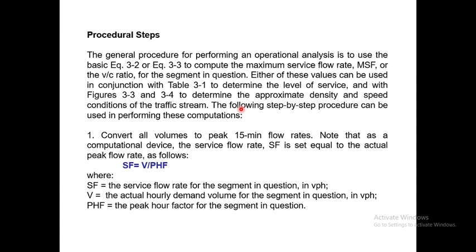The other equation which is very useful here, and in the first step very important: you have to convert all the volume to a peak 15-minute flow rate. So for converting, you have to use this equation. SF, or service flow, which is desirable for us, we always use SF, is V over PHF.